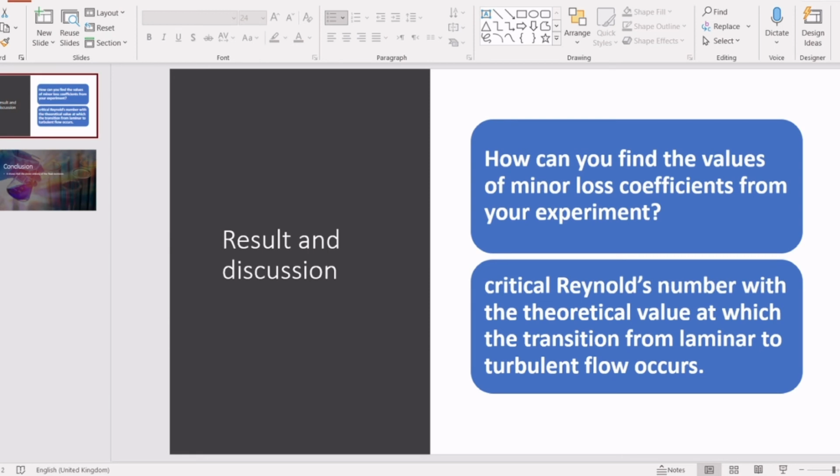In the same way, some elements of the system will maximize the fluid energy, and there are components of the system that work against the fluid, reducing its energy, velocity, or momentum. Small losses in the pipelines are significant contributors. The kinetic energy term is used to quantify the minor head loss, which is the energy loss due to the system component. The minor head loss can be calculated by using the equation of the head loss.